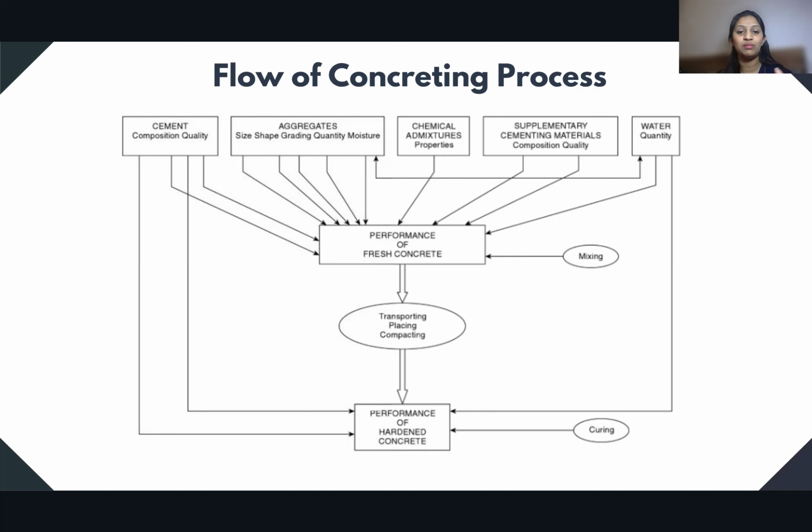So again, the water will be linked to this hardening, because curing definitely involves gunny bag curing, or it might be water spraying. There are multiple ways you can try to cure the concrete that has been cast. This definitely determines the strength gained by the concrete, and the durability of the whole structure will be gained at this particular stage. So this is where we will be involved with the complete flow of the concrete.